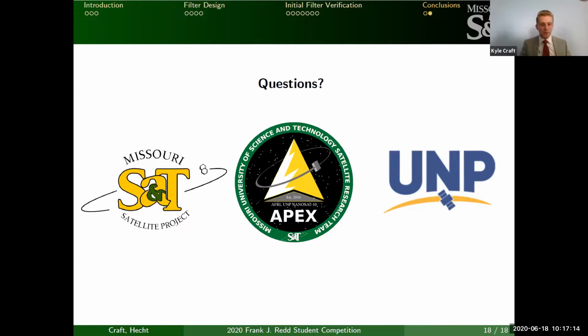Okay. Have you evaluated the sensitivity of positional accuracy to delays in the star tracker solution? So if you had dropouts or occlusions? We have not. So we could incorporate some kind of correction as we did with the GPS pseudoranges, where we correct those time biases on our GPS measurement timestamps. That could be a possibility that we could look into, but currently we're not looking into correcting anything from the star tracker as far as the timestamps go. Yeah, we just consider the uncertainty, and we assume that the satellite will not have angular rates that are that high, because that would be kind of detrimental to the mission as well.